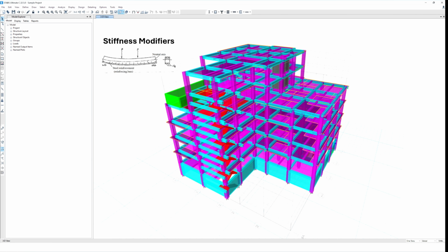Concrete is strong in compression but weak in tension, as you know that. Under external loads, the tensile stress in concrete exceeds its tensile strength, causing cracking. Uncracked section analysis assumes concrete is perfectly elastic and resists tension, which is false after cracking. This leads to overestimation of stiffness, causing less deflection and more internal forces. Inaccurate prediction of crack width and spacing is also a result of this.